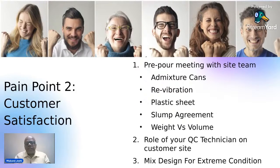So we have to train our transit mixer operators. They are going to carry cans of 50% water, 50% plasticizer, a 5-liter can. And in your pre-pour meeting, you are going to explain this point nicely to your client, and you will make him agree, you will make him sign that in the eventuality of delays, we are going to add this plasticizer in your presence, mix through the drum by 1 minute of rapid mixing, and then use that concrete. So this is the point number 1, which you will make your client to agree.